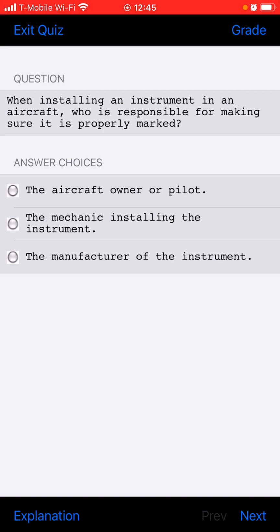What could cause an AC electric motor to run too slowly? Lack of lubrication, defective wiring, low applied voltage. What could cause an AC electric motor to run too slowly? Lack of lubrication, defective wiring, or low applied voltage.